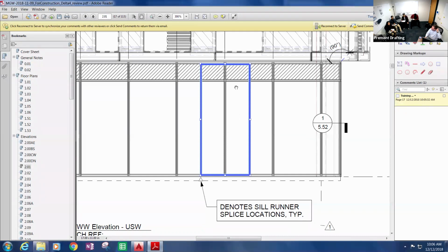First, can you define what deflection is? So deflection is the bending of things. Whether it's from dead load or wind load, floor slabs deflect when you put a bunch of people on it. So the building engineer, when they're looking at the structure of their building, has to worry about live load deflection. So again, deflection is when you have loads applied, and it can be dead load deflection, wind load deflection, or seismic deflection.